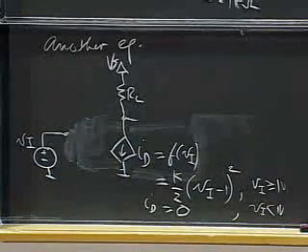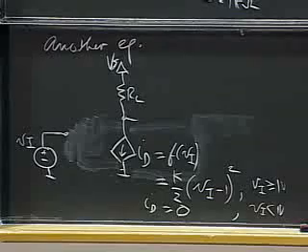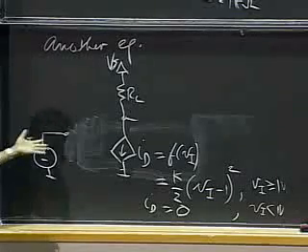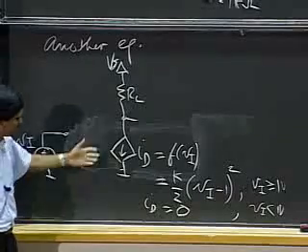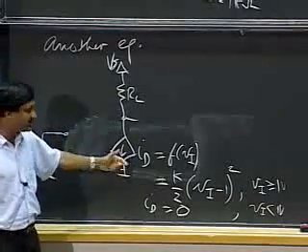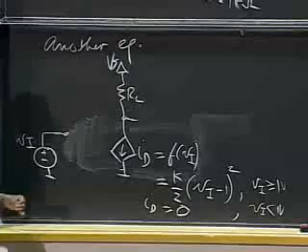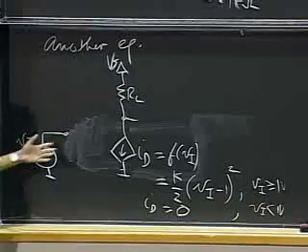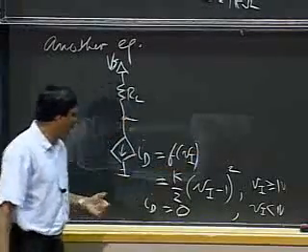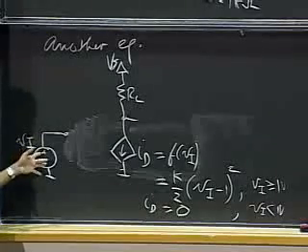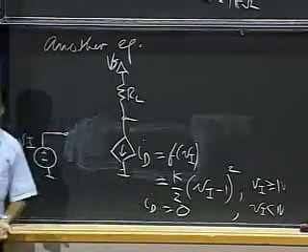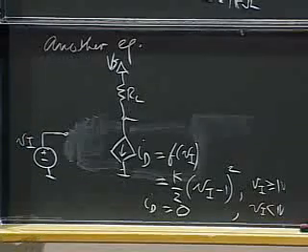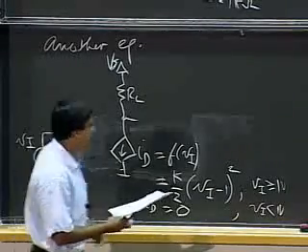Okay, but it's a dependent source, and it can have various forms of dependencies on the input. I just picked an example of some hypothetical, or as yet hypothetical, dependent source, the current through which is related to the input using a square law relation, K/2 times (VI minus 1) whole squared, as long as VI is greater than 1. And if VI is less than 1, then the current is simply 0. It shuts off.